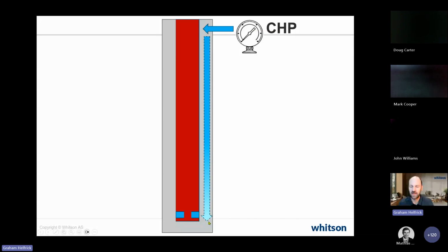Once we calculate the pressure to the end of the tubing, we do another calculation, a multi-phase flow calculation from the tubing down to the perforations. So this is one of the ways to calculate the bottom hole pressure if we have a downhole choke. There's a bit of a caveat, and that is fluid level or liquid level in the annulus.